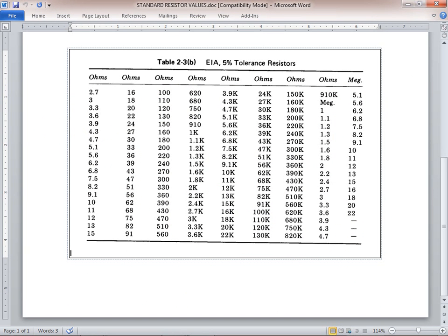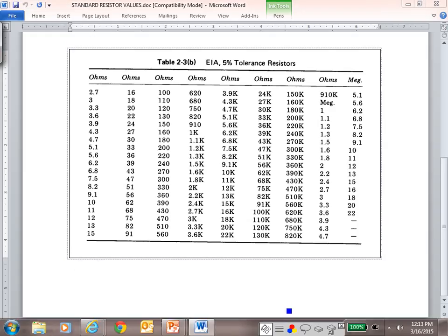So what did we calculate? We went 5.8. So what'd y'all calculate for RB? Yeah, 5.8K. So we drop down here. It looks like we might use a 5.6. So what would I do? I'd say 5.6 times 1.05. Y'all understand what the 1.05 is? That's increasing it by 5% for us, right? And what does that come up and give me?